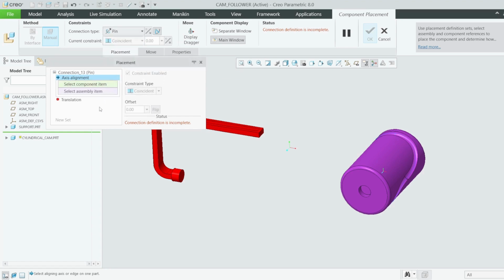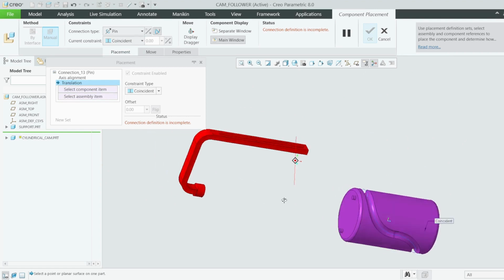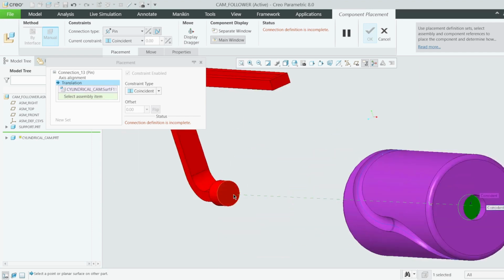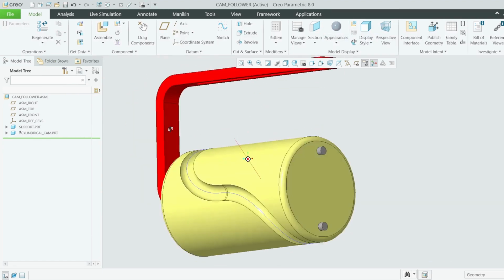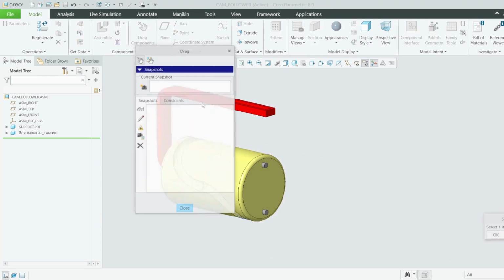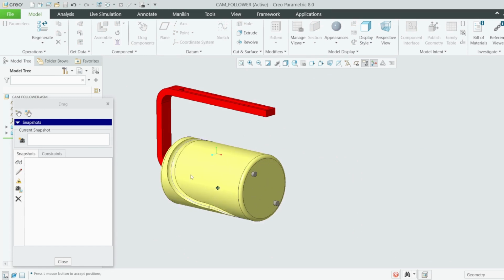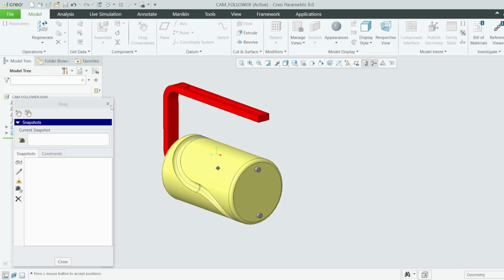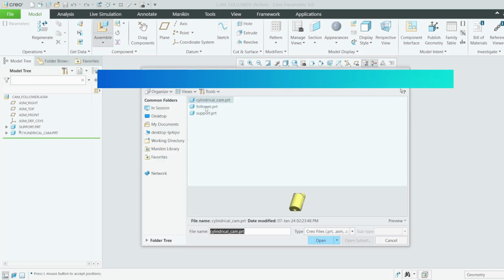In the pin, you select the surface that is going to rotate with respect to this surface. Again, you need to select the surface onto which we are going to be touching. This surface should touch this surface here, and you flip, then say okay. Those are enough. If you select drag here, let's see whether it will rotate. This one here, you can see it is rotating because I've used pin connection. It doesn't move laterally, it only exhibits a rotary motion. Okay, and next we need now to assemble our follower.